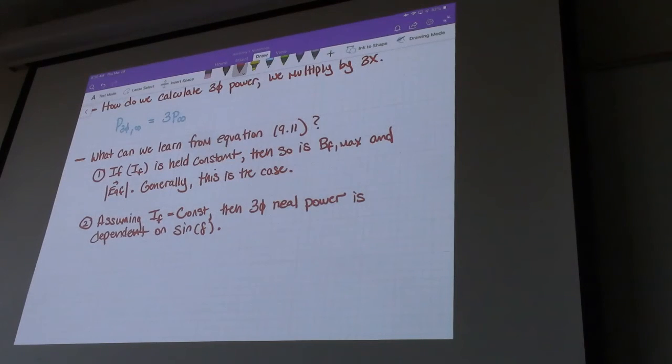So the phase shift between this infinite bus that we're assuming, right, the terminals of the generator, and the internal EMF, okay, that EAF value, the phase difference between those two values is going to have the hugest effect on how much real power our machine is generating.